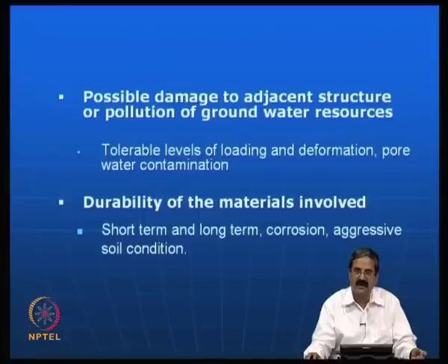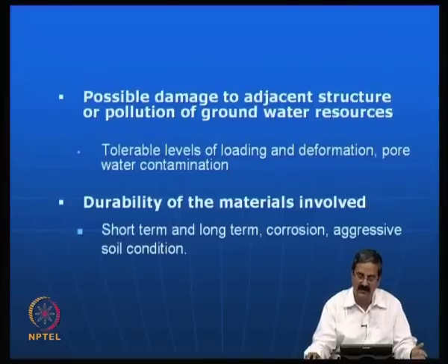I will show you, in fact, in a nearby area they are using micropiles. Micropiles one can use for apartments where there is no problem of deformation at all. There is a 3-storied or 4-storied apartment, next to that they are cutting vertically because they have already used some sort of micropiles there. So that way one should know what are the tolerable levels of loading and deformation.